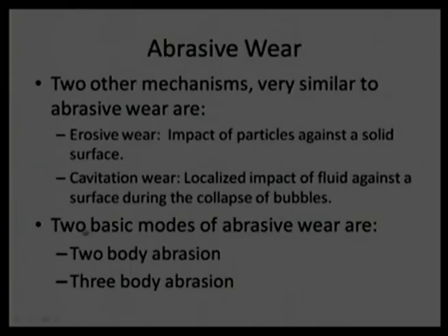Now, further we will come to the modes of wear. Abrasive wear can be further classified based on whether it is asperity versus asperity or particle versus asperities. If asperity versus asperity interaction occurs, we call it two-body abrasion.